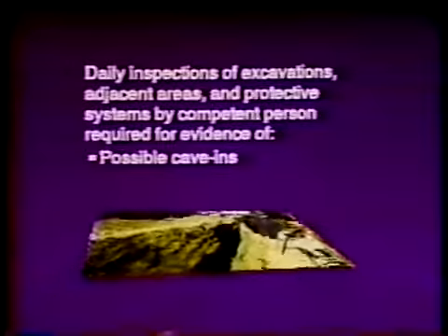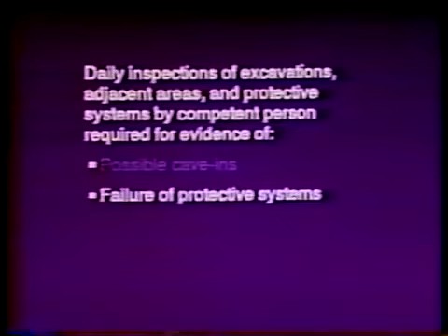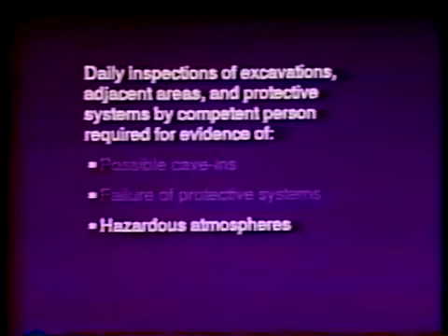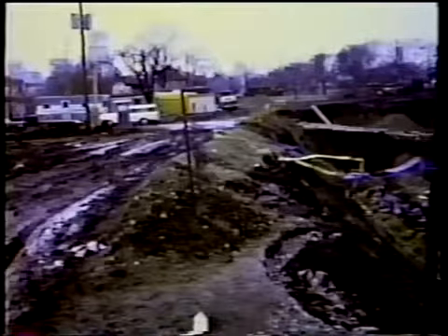Daily inspections of excavations, the adjacent areas, and protective systems must be made by a competent person for evidence of a situation that could result in possible cave-ins, failure of protective systems, hazardous atmospheres, or other hazardous conditions. Excavations subject to heavy rain runoff are to be inspected by a competent person and, as necessary, precautions instituted to protect against the hazard. Inspection shall be made after every rainstorm or other hazard-increasing occurrence.